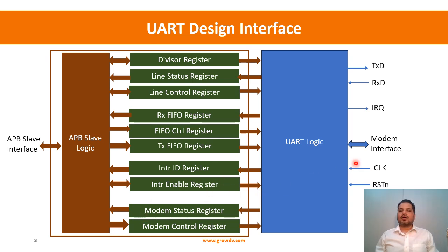And then we also have this modem control interface. We are not going to go very deep into it. Then you have the modem control register and a modem status register. For all practical purposes, there are a bunch of pins. Whenever they change states, the status register gets updated, and through the control register you can control on which of the changes you want to be interrupted. So you can do that.